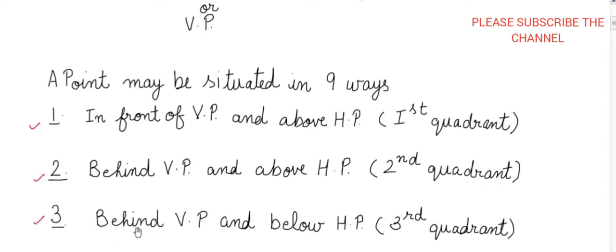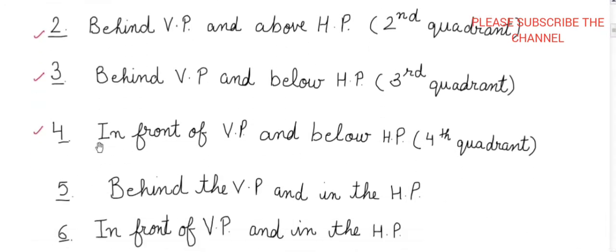Third case is the point is lying behind the VP and below the HP, which is also known as the third quadrant or third angle projection. Fourth case is the point is lying in front of VP and below the HP, also known as fourth angle projection, or you can say the point is situated in fourth quadrant. So these four cases are very important from the exam point of view. We will study these four cases in great detail and the rest of the cases in brief.